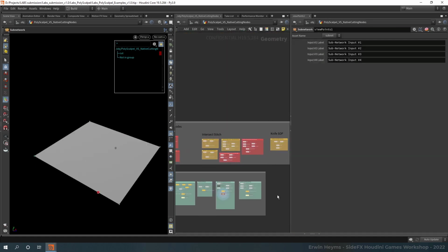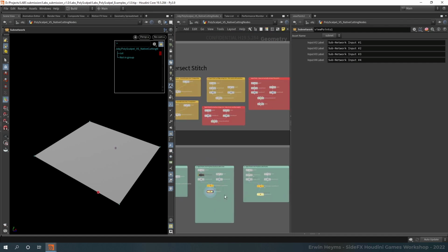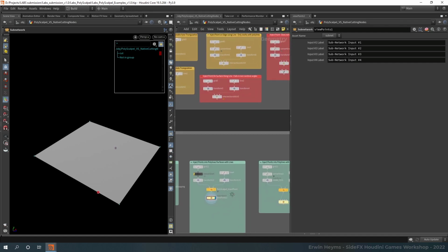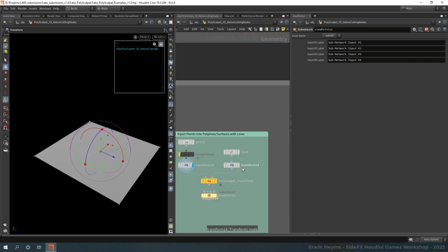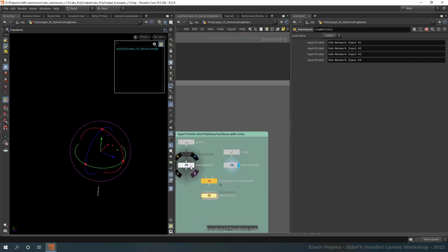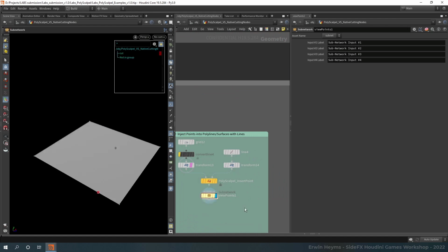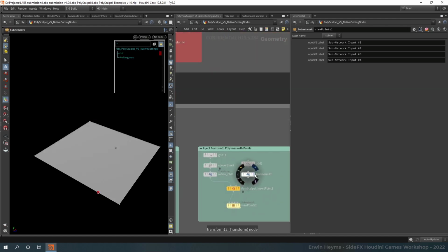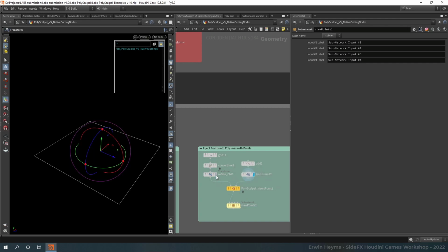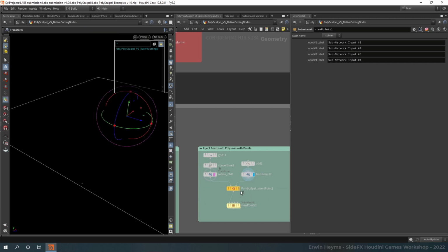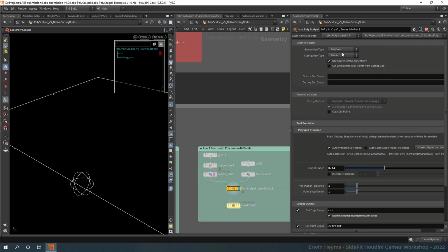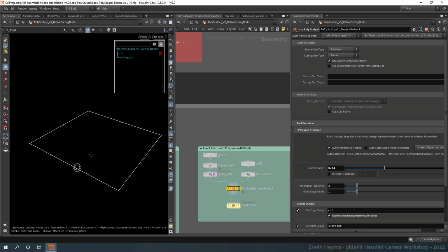The rest of these examples basically demonstrate that we are able to cut our geometry using edges as well. Over here I am cutting a surface with an edge, and that works just fine. Or I can use a point. In this case I can take a point on an existing edge or near an existing edge, and if I set the tool into polylines cut with points, because these are polylines, I'm now injecting a point into this edge and dividing it into two primitives.